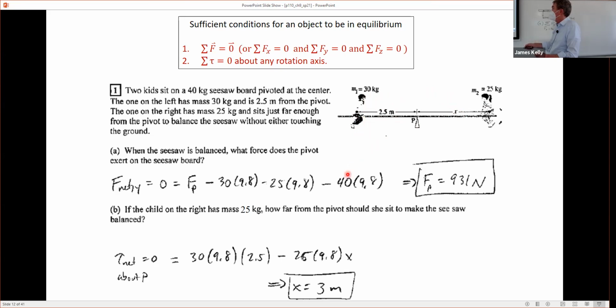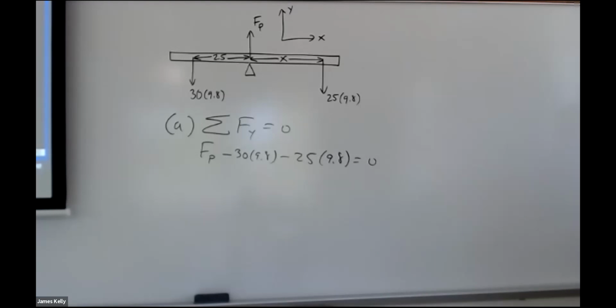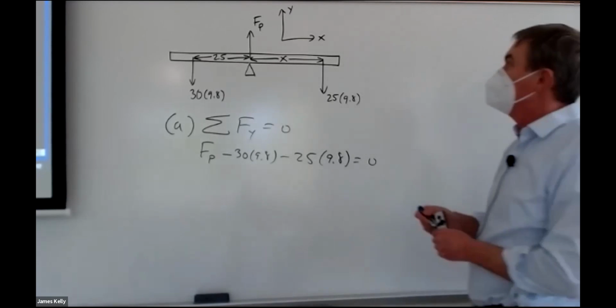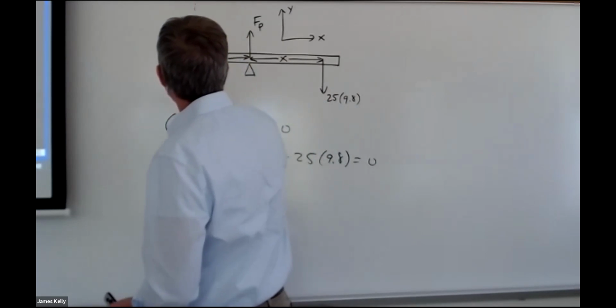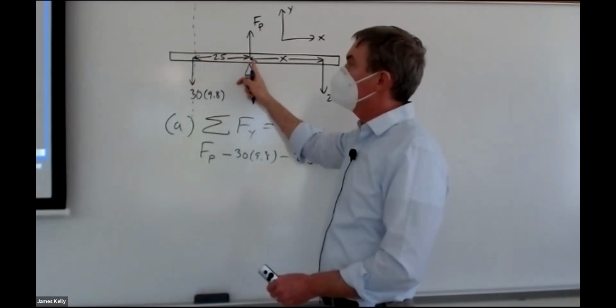Everybody okay with that? That's why I'm putting a plus sign over there. It's the magnitude of the force times the moment arm, right? The force is going in this direction. So I draw the line, and I can't say this too many times because people forget it: draw the line that contains the force vector to find the moment arm, and then ask what is the shortest distance to the rotation axis?